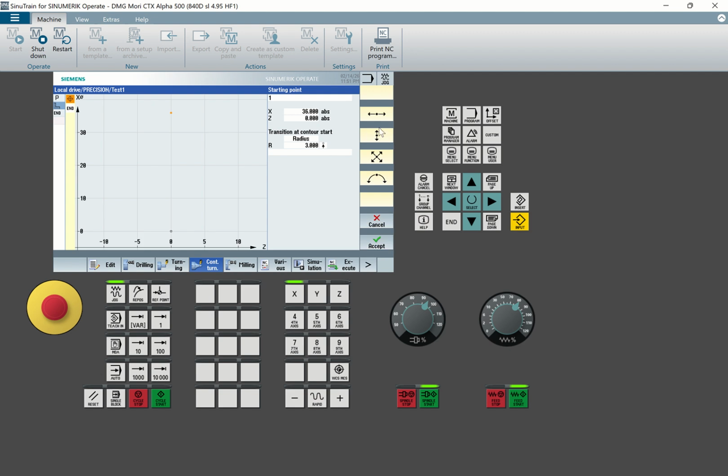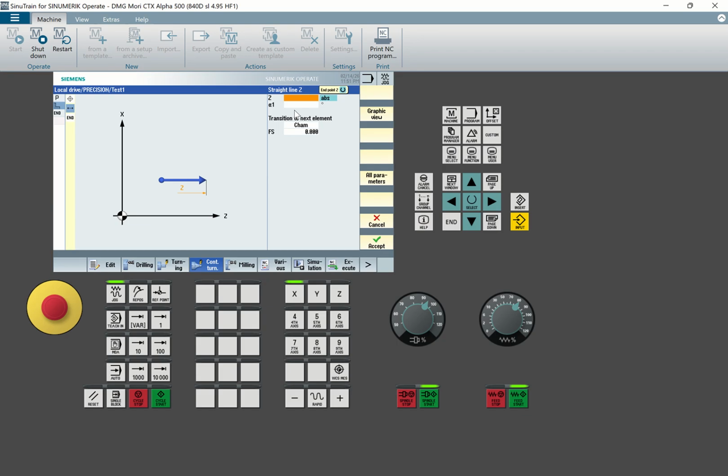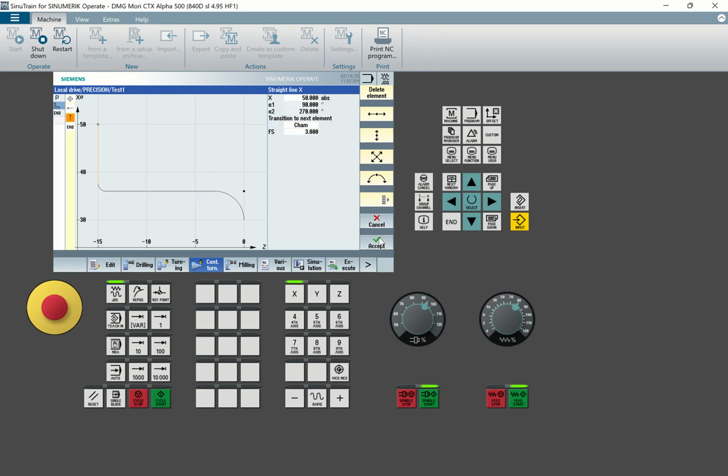Then from there we are going to horizontal. From this horizontal I'm going to minus 15. Accept. I don't have a radius, but because of where the tool is cutting, I can put a radius of 0.5 depending on the tool I'm going to use. Let me put 0.8. Okay, and then from there we go to vertical. A vertical, I have a diameter of 50 with a chamfer of 3, so I can put chamfer of 3. Then accept. You see on the graphic area it is sketching.